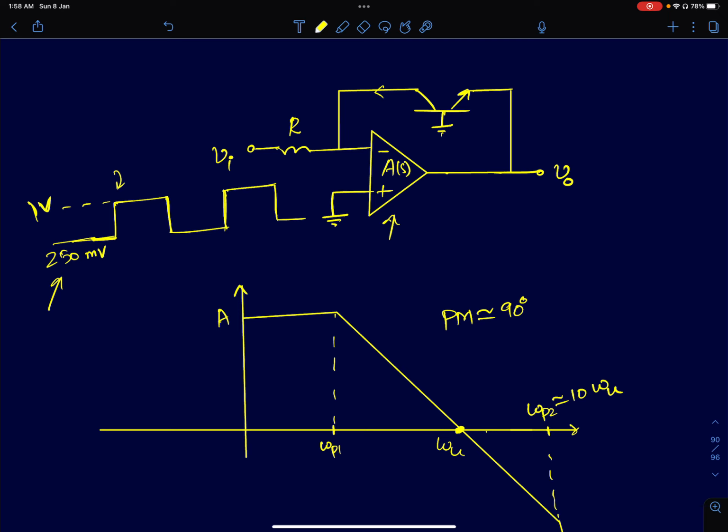The circuit shown here is a logarithmic amplifier. Logarithmic amplifiers were popularly used in the first generation analog amplifier circuits. They were used for voltage multiplication, and they were used for voltage division. Again, as I said, op amps can be used to realize a range of nonlinear functions. So this is one such circuit. We'll see its operation in a few moments.